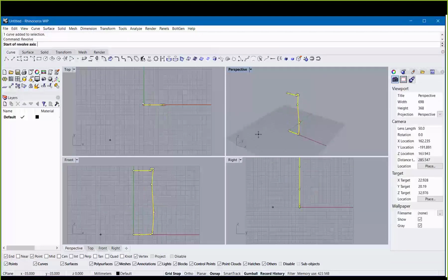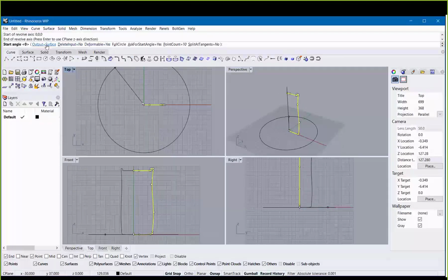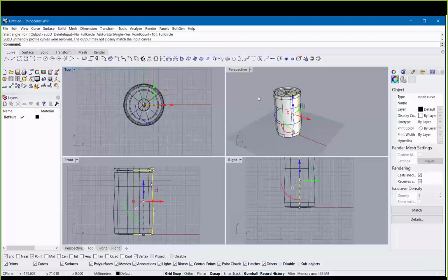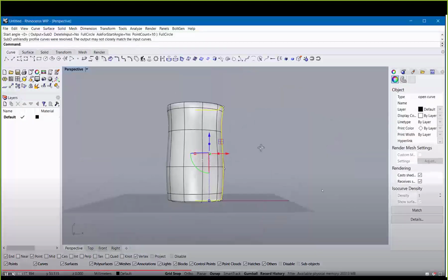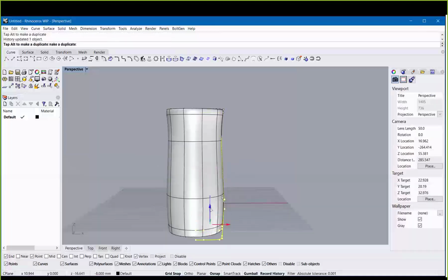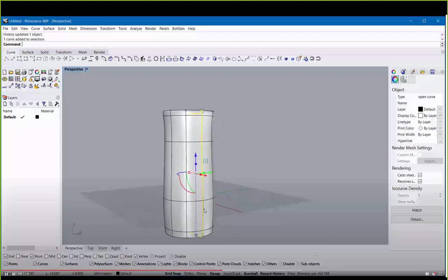And once you run the revolve command on this curve, the resulting object, if you choose SubD friendly, will be a SubD object. So right now, we've already seen you can start editing, selecting edges, faces, and more.